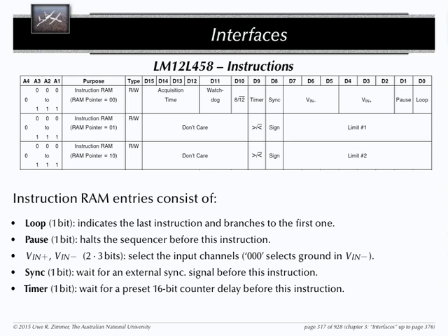But you have a bit which says, this is the last instruction in my sequence of instructions. Please go back to the beginning, to instruction number 1. And it starts again. If you don't set this, it takes the next instruction. So there's only the information for the sequencer. Is this the last instruction in my sequence, or is there still something following after that? You can tell it to pause at this point and to wait for a specific event.